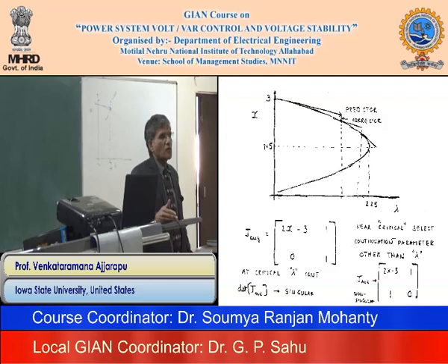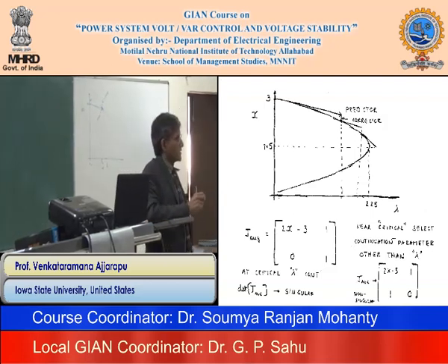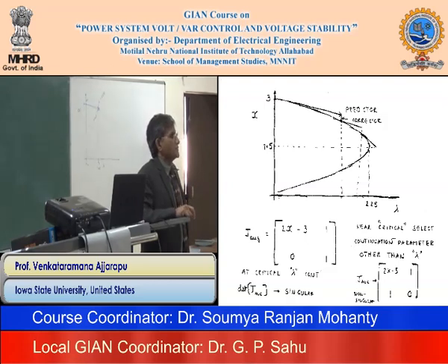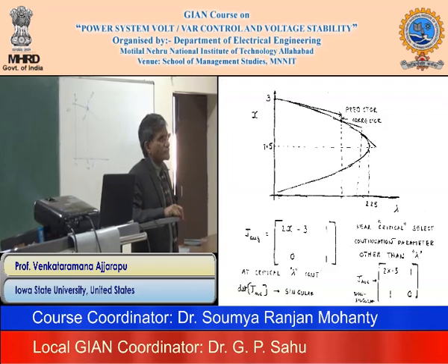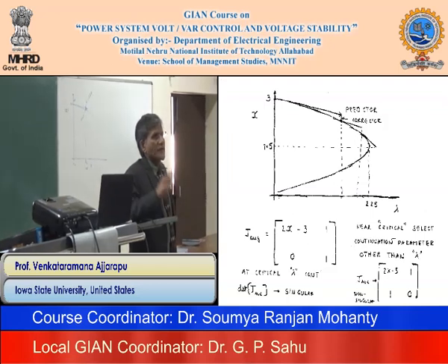But as I mentioned before, in this formulation, when we say lambda, that should be an independent parameter, or independent variable, that should not depend on x. So if I take the P, real power, we know if it is a non-constant power load, the real power depends on the voltage, that is x, right? So I cannot use P as the parameter.